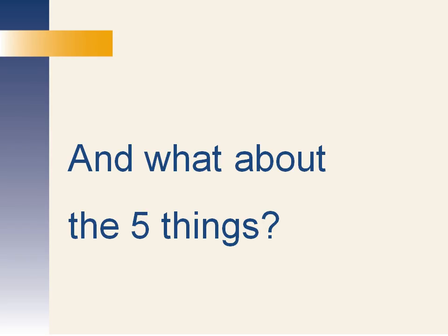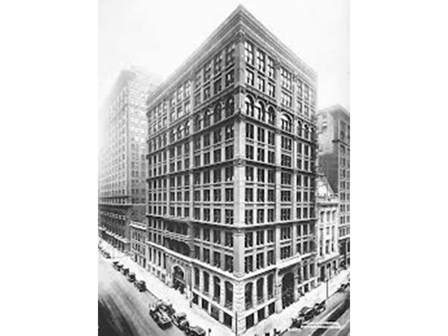It's also important that we talk about those 5 things, which of them are being addressed and which are not. And I guess it is no surprise at this point that the work to date does very little to address the 5 things. The 5 things are things we know today. They knew very little of these things back then. The practices of the day tended to compensate, however. Heavy masonry infill was very common in buildings, as was the presence of uncalculated strength and stiffness. The analysis methods of the era were conservative by nature, and although the term skyscraper had come into existence, it described buildings like the Home Insurance Building shown here. They were on the order of only 10 stories tall.